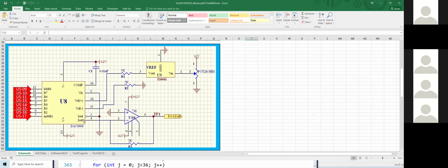Okay, and that 2 milliamp coming out, we cannot take care of current out. That's why they're adding this circuitry. That means the circuit is converting current to voltage. That means 2 milliamp coming out times 5K, so you're supposed to get at that point almost 10 volt. Okay. If not, then whatever they show on the circuitry here, you just take it.